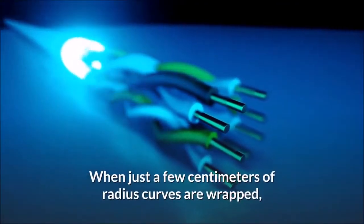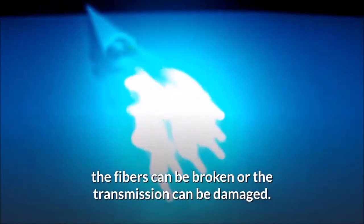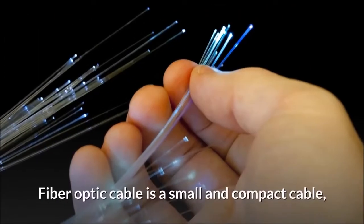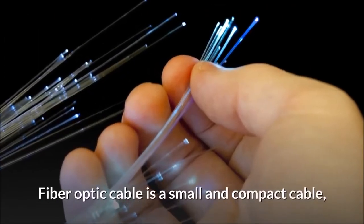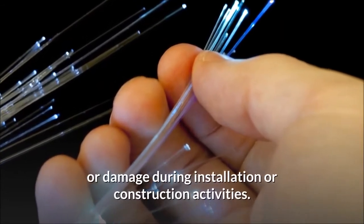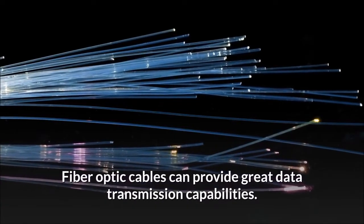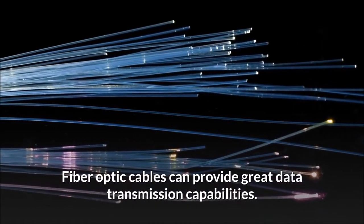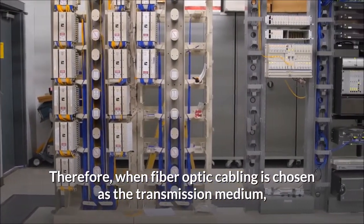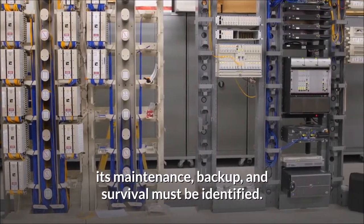When curves of just a few centimeters of radius are made, the fibers can be broken or the transmission can be damaged. Highly susceptible. Fiber optic cable is a small and compact cable, and it is extremely sensitive to cuts or damage during installation or construction activities. Fiber optic cables can provide great data transmission capabilities. Therefore, when fiber optic cabling is chosen as the transmission medium, its maintenance, backup, and survival must be considered.